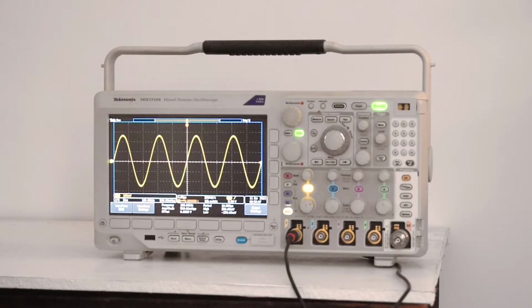All this is very simple, but it becomes more critical when certain operations, the results of which are not visible on the screen, are performed, such as bandwidth limiting. In order to reduce broad spectrum noise, you or another previous user may have temporarily cut the bandwidth down to a lower level. In this event, the reduced bandwidth survives power cycling, and you may wonder why you are unable to acquire and display high-frequency signals up to the instrument's full bandwidth.